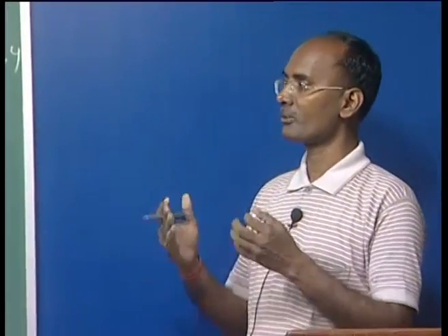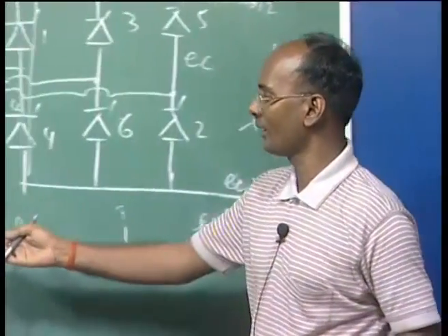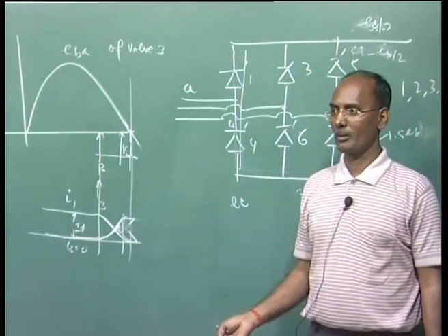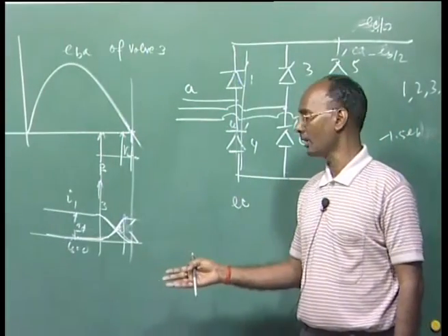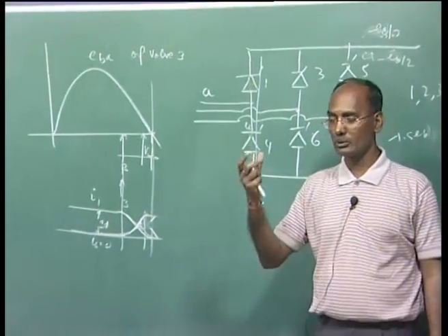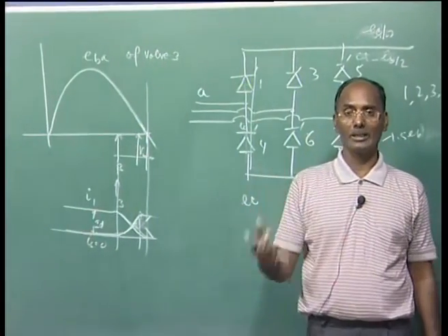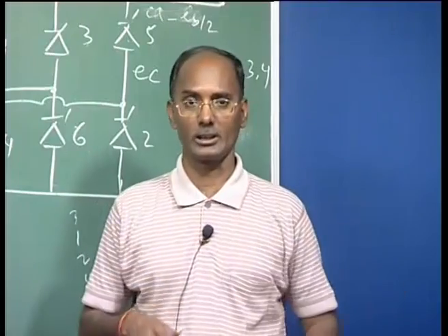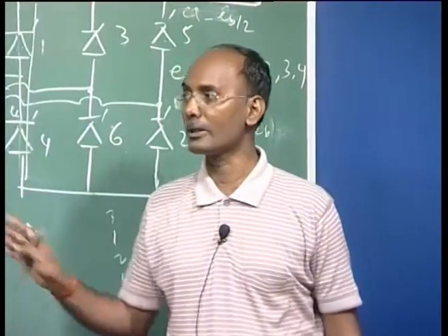In an inverter circuit, this is a very common and persistent phenomenon, and if one commutation failure occurs in one cycle and it is over, it hardly matters. But it should not occur continuously, otherwise your bridges will be highly stressed, and the voltage across them will have very sudden changes here and there. So it should be properly taken care of.